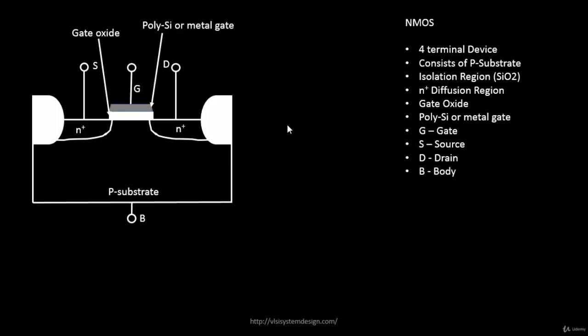The most important topic that will drive all your SPICE simulations is the threshold voltage. Why am I emphasizing the term threshold voltage? Because when we do SPICE simulations, the terms involved in describing the threshold voltage of an NMOS transistor are the models that will represent your NMOS transistor. I'll come to that very soon.